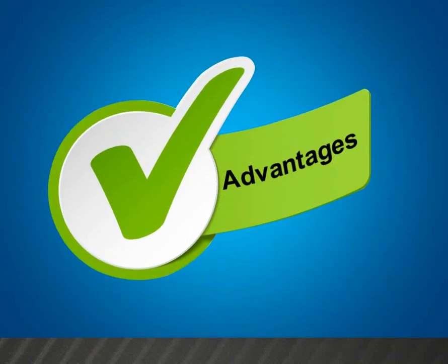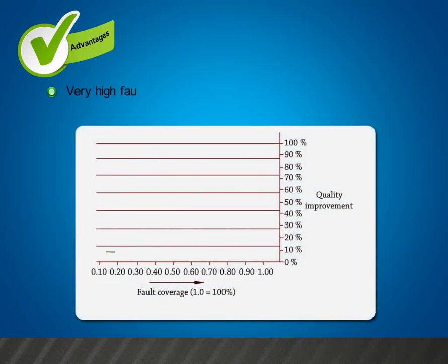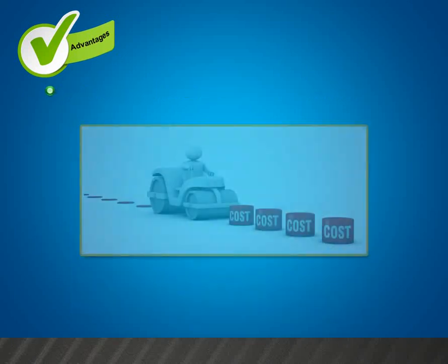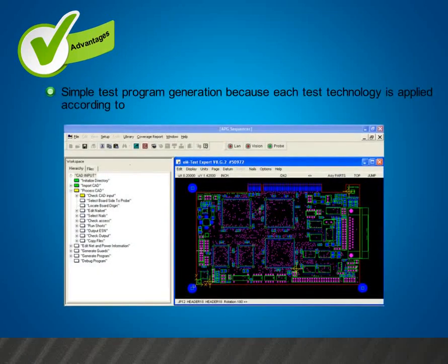Advantages of in-circuit testing: very fast total system, very high fault coverage also for highly compact PCBs, reduction of nail bed adapter costs, simple test program generation because each test technology is applied according to its core competence.